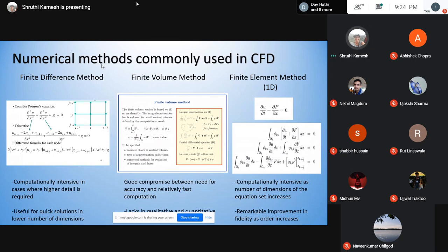Say, for example, if I get a solution from a finite element or finite volume method which says that my flow through, around a sphere in 2D or 3D, ideally you'd imagine that it would go around the sphere and not through it. But if I'm getting a solution which says that it should go through the sphere, that is inherently entropy violating, which is not physically satisfying. So you would not take that as a solution.